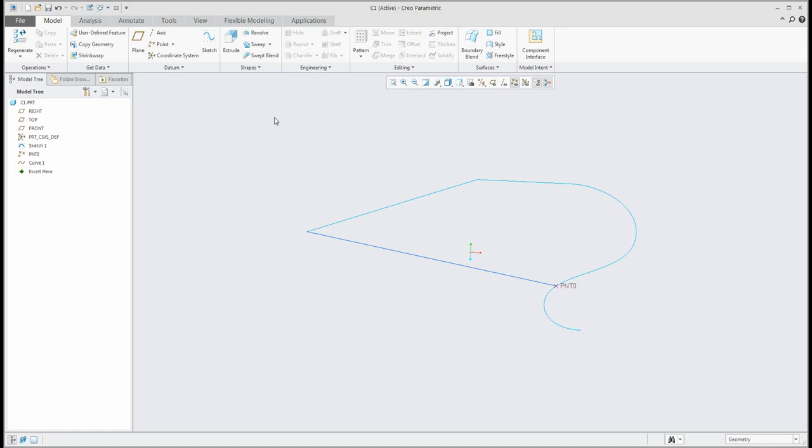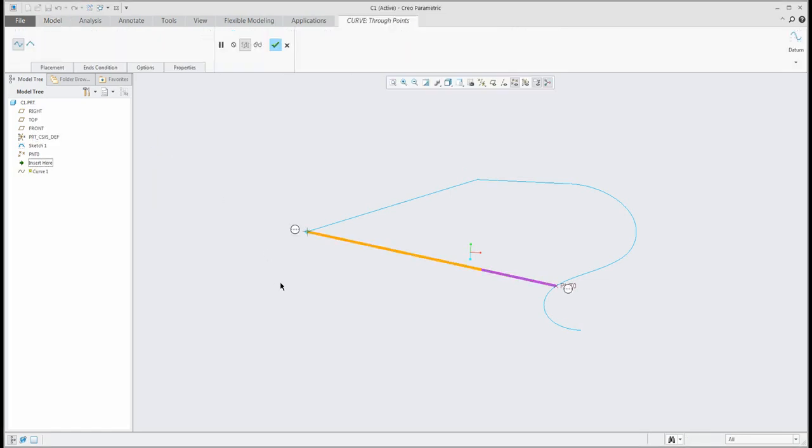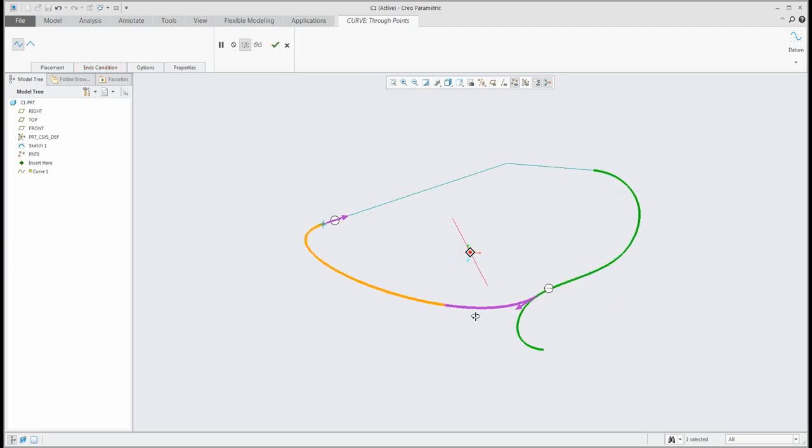The created curve is possible to edit. What does it mean? If you select the definition again, you can specify the tangency of the point. So over here I can use the right mouse button and specify the tangency or curvature or normal specification. For example, I will select tangent and specify the connection. You can choose the tangent direction, whether it goes this way or the opposite way, and I can continue on the second side again here, and again you can change it.